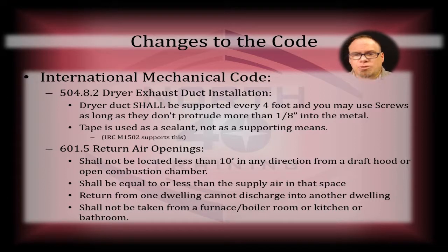It shall be equal to or less than the supply in that space. Well, most of us are accustomed to seeing returns and supplies in nearly every room, except not a kitchen oftentimes, and hopefully not a bathroom on the returns. So you've got to have supply into the space that's at least equal to the return being taken out of there.